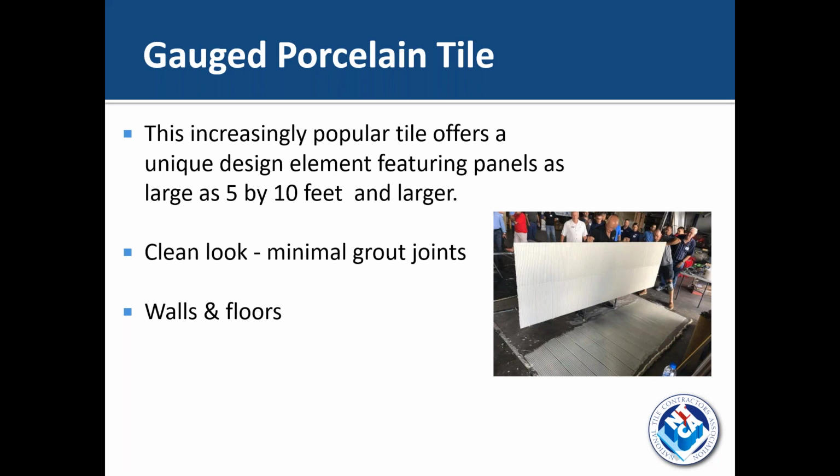You can also imagine that it takes a little bit of time to apply all of that adhesive, and sometimes you'll have a crew of 4 guys, maybe 2, applying it to the floor or the wall, and then 2 more applying it to the panel. And open time obviously is critical, because you don't want that to skin over before you have a chance to embed it. So open time is also a key attribute for an adhesive for this application.